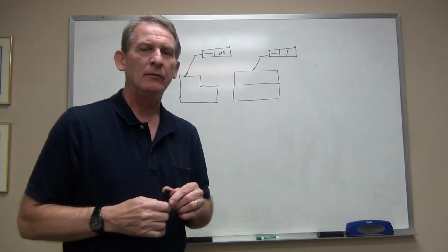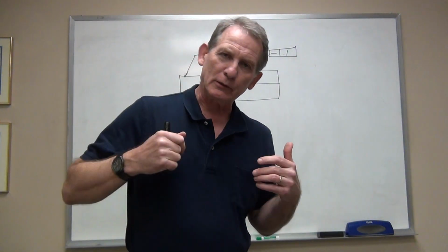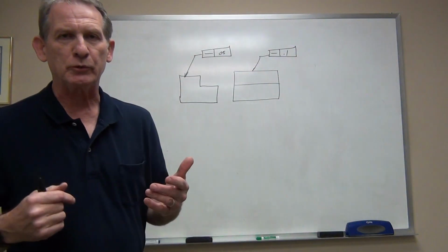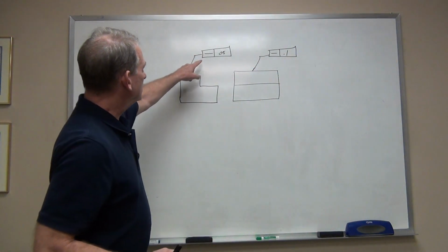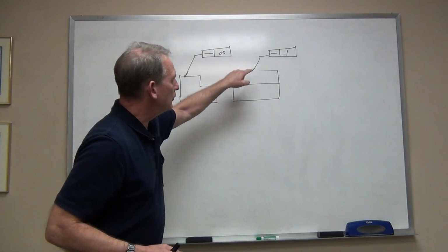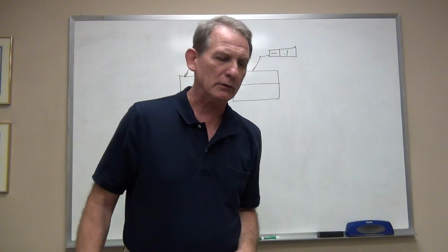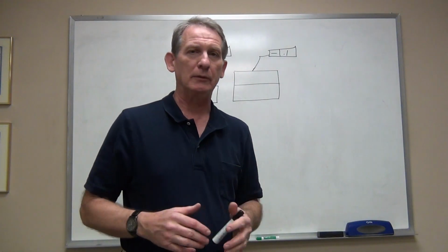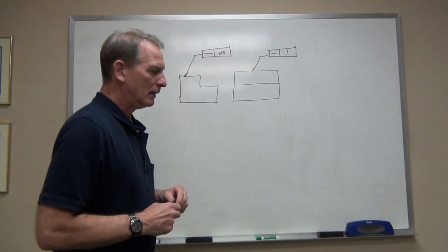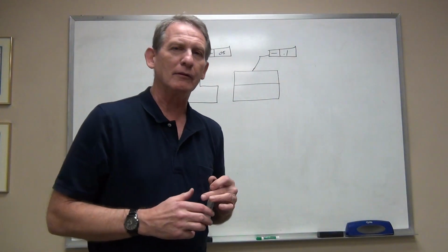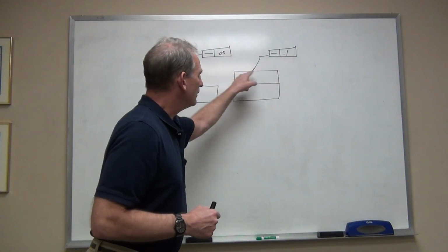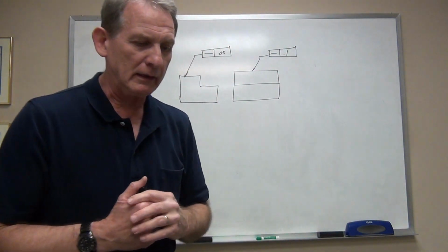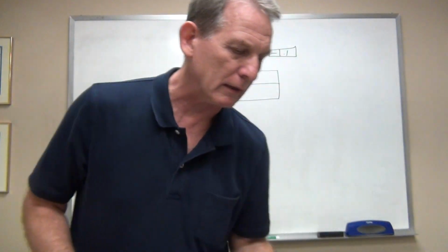We are controlling linear elements. First thing we're going to ask ourselves, are we controlling linear elements on the surface or some sort of derived element? Since the feature control frame is pointing right to these surfaces, the top of this block, we know that we're controlling the surface elements. In other words, there's an infinity of lines along this surface, along the top of this block that we can control, and each one of them has a control as noted on the drawing.